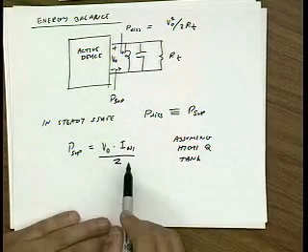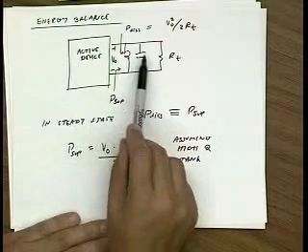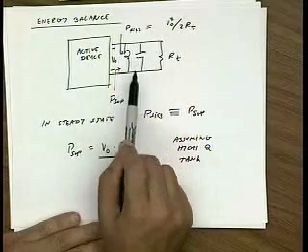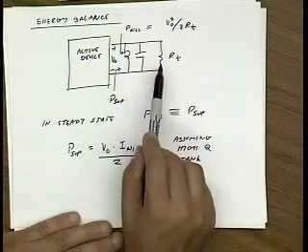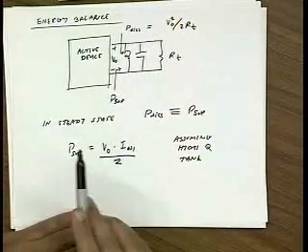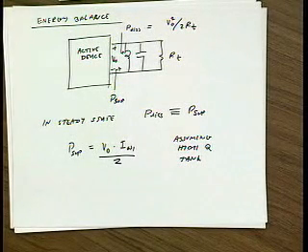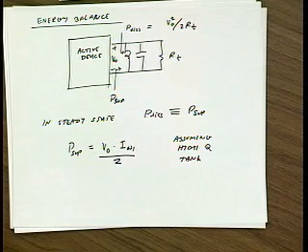In other words, the higher harmonics of this active device see this capacitance, and that's reactive energy. So they're not actually supplying energy to the tank. We're assuming that the only energy being supplied to the tank is from the first harmonic. Okay? Now this assumption is very close to what we said last lecture when we assumed that the output was sinusoidal and we used the concept of the large signal GM. Okay? Any questions up to here?